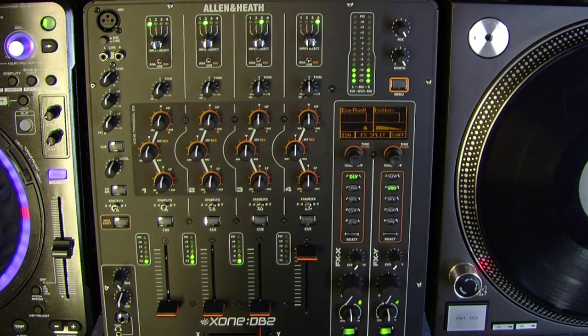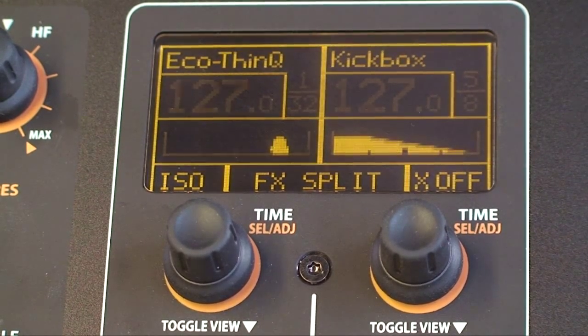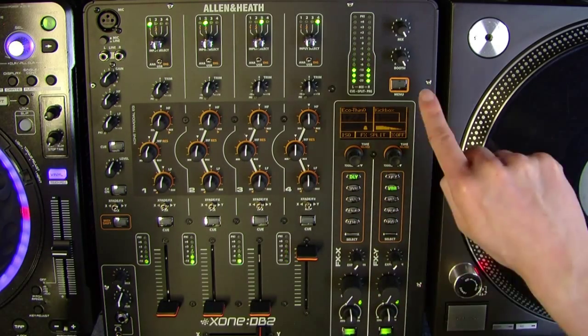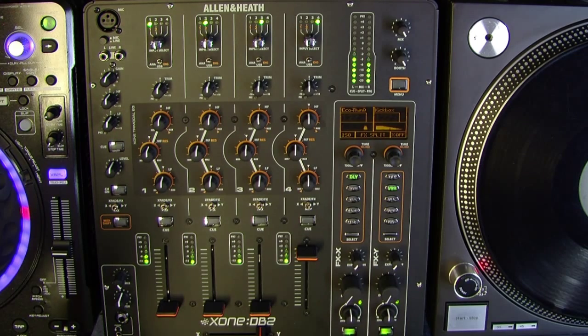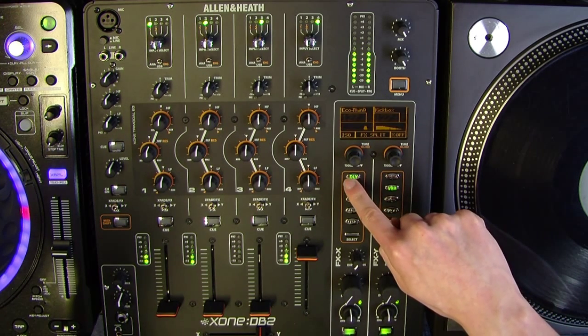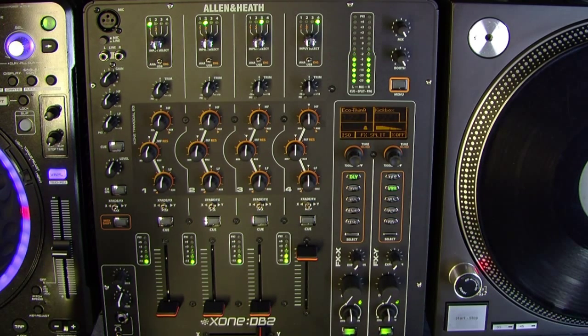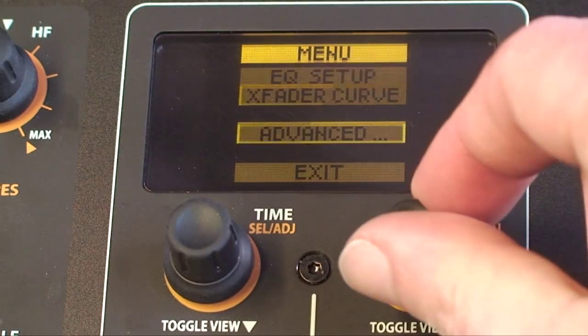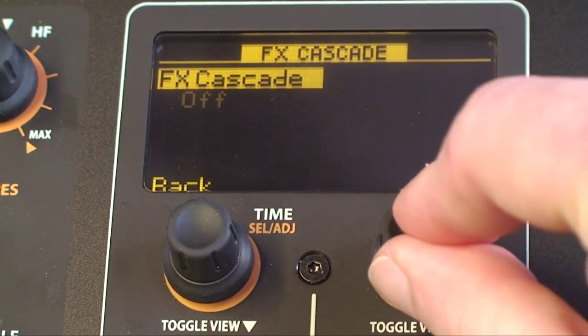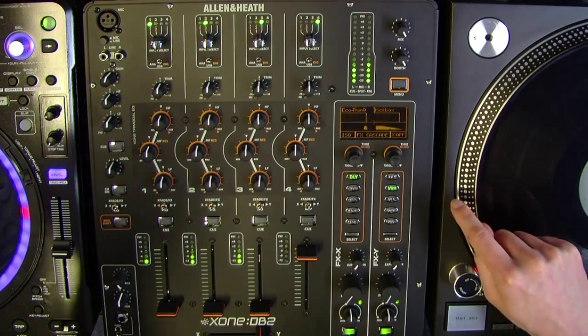From version 2 firmware, the 2 effects engines can be cascaded or chained to run the output of effect X to the input of effects Y, allowing the audio to be processed by any combination of 2 different effects. To configure the DB2 for cascaded effects, open the Advanced menu and scroll to Effects Cascade. Cascade mode can be turned on or off by pressing the Select Adjust encoder when the item is highlighted.